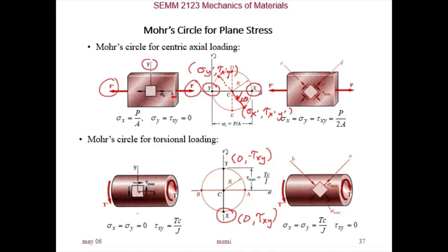The principal stress is given by point A, and also point B, right? Point A and B. So if you look here, the difference in angle is 90 degrees. Therefore, you know that the axis or the plane where principal stress occurs will be 45 degrees on the actual object outside. Okay, it's 45 degrees. So that's the tip for you. You have to remember those clues. They are very important to help you solve your problems in test or examination.